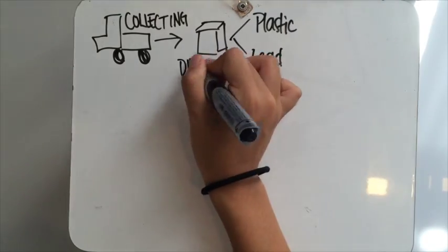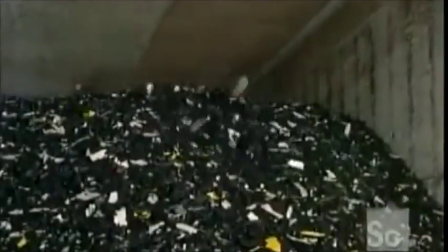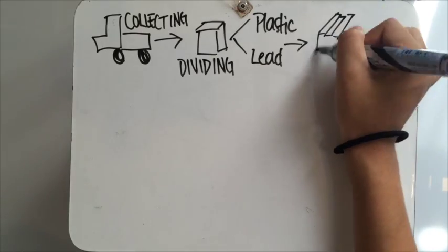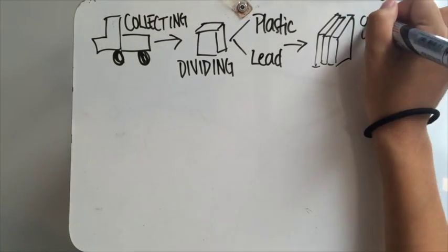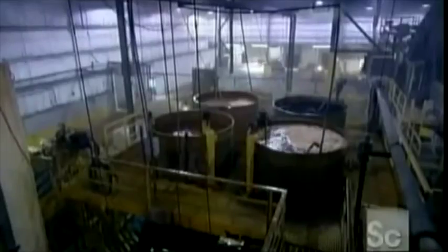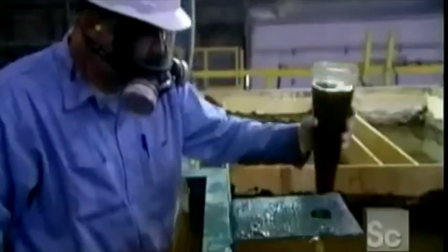acid. This is done by smashing the plastic and the lead into tiny pieces with a rotating hammer. The pieces are put in water and the heavy lead part sinks, while the plastic parts float to the top. The plastics are cleaned and sent to a plastic recycling plant. The lead-acid batteries have acid, so the acid is neutralized by adding an industrial compound similar to baking soda. It is a base, so it neutralizes the pH of the acid.